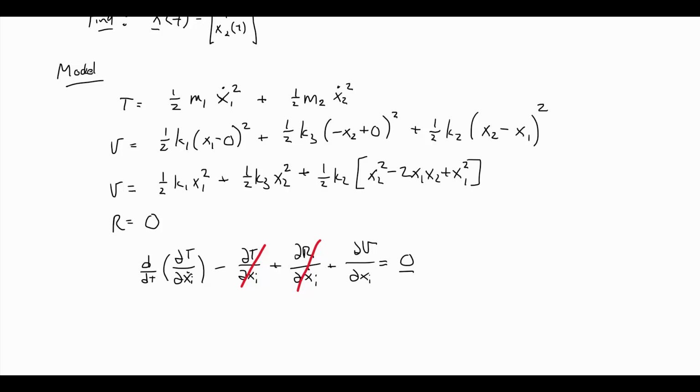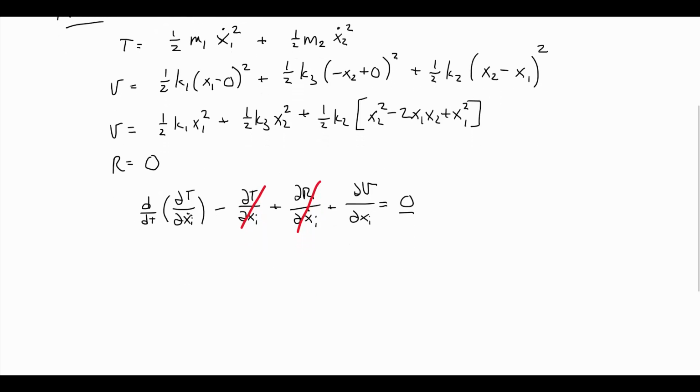Now notice here, unlike what we saw in Unit 1, I have ẋ sub i, x sub i, because I'm going to do my Lagrange equations twice. I have to do it for each independent degree of freedom. In this case, x1 is my first degree of freedom and x2 is my second. So for my first one, I'll write it out in long form here: d/dt ∂T/∂ẋ1 plus ∂V/∂x1 equals 0. All right, so now it's a scalar equation because I'm doing it specifically for x1 first.